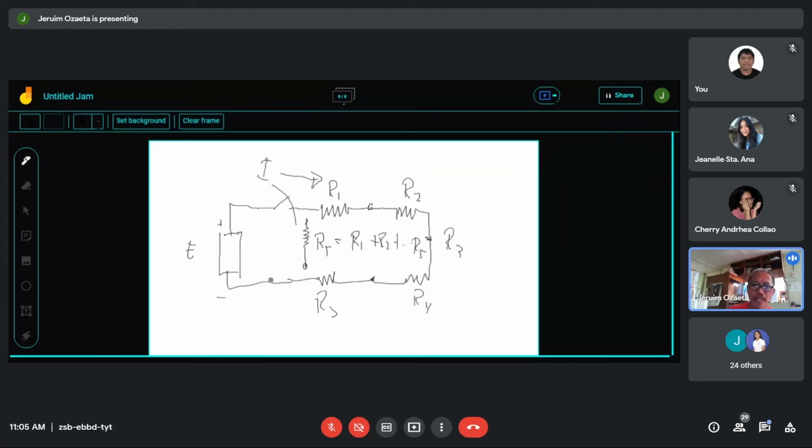So what do you see here? What current flows through R1 is the same current. So we can say that the current that flows from the source E is equal to current at R1, is current at R2, etc., R5. We call this kind of circuit a series circuit. Series because it follows from one after the other.